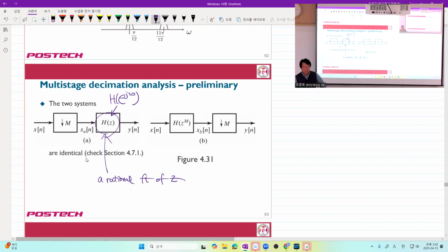As I told you, the Z transform of a DT signal is not always a rational function of z, but in order to implement it, we'd better approximate it with a rational function. In that case, we can use an alternative representation of the system by using LCCDE, linear constant coefficient difference equation, which directly gives us how to implement the system using delay, adder, and scalar multiplier.